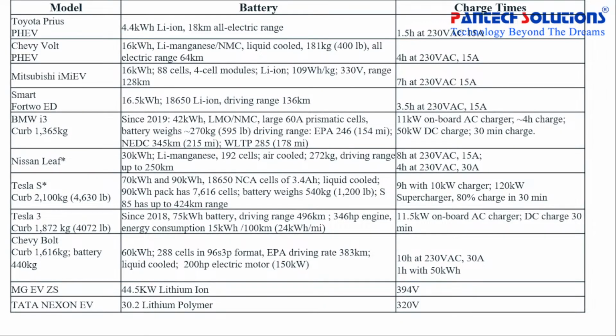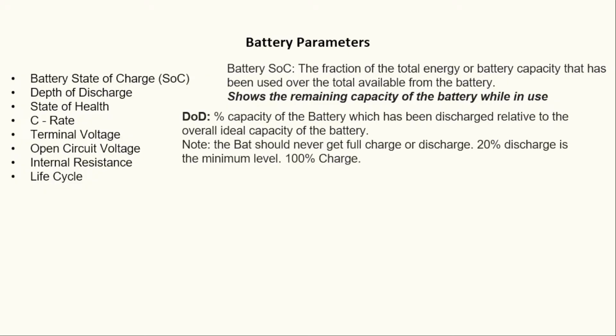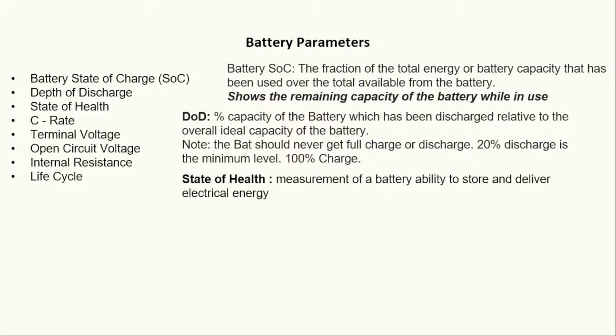It's just a case study: what type of vehicle, how much capability, and what the range is, you can know here. If you want in-depth knowledge about batteries, you have to know battery state of charge, depth of charge, and also C rate, thermal voltage range. You have to calculate these things. For example, for the certain range of motor you are choosing, you have to calculate what range of battery to choose. Without these things, we can't imagine developing that.